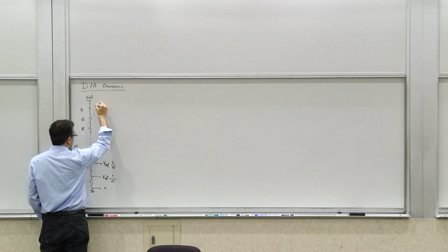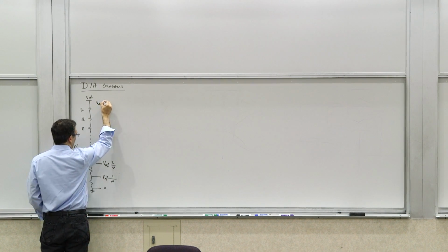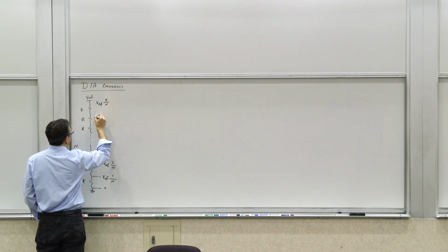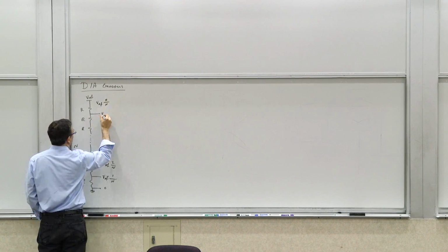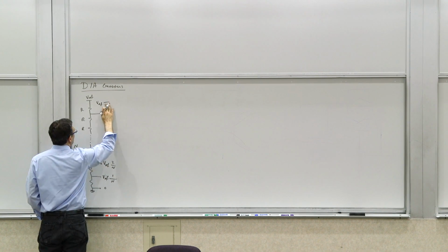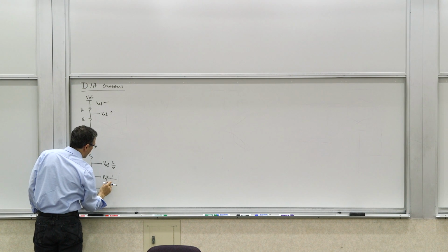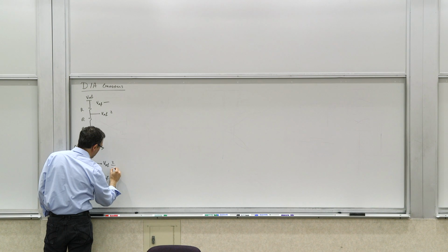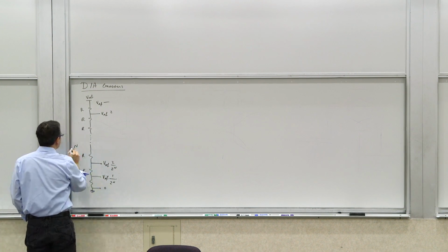So this is basically Vref times n over n. And the one before that is going to be Vref times... I'm sorry, actually this should be, if there are N bits, let's call this 2 to the N, if this is capital N. So there are 2 to the N resistors.